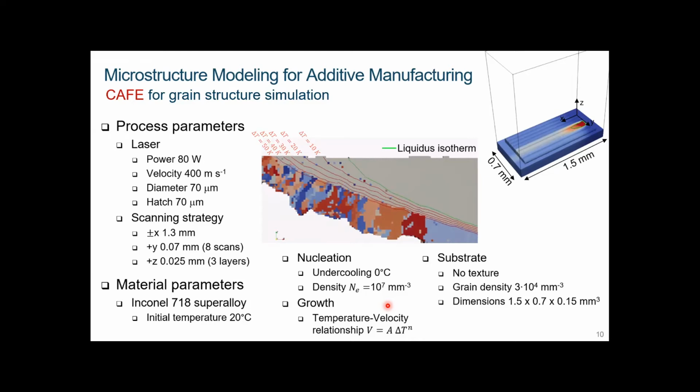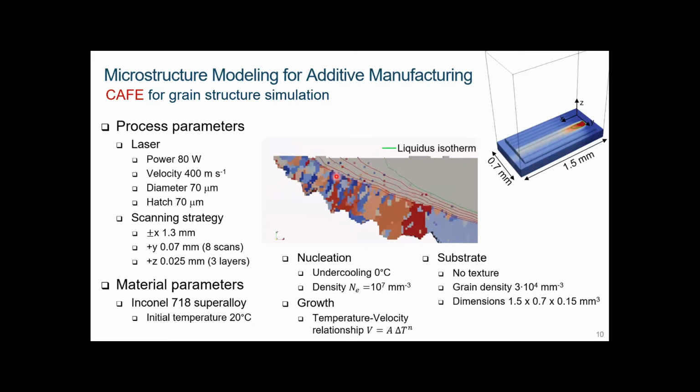Okay, so that's an illustration showing how the liquidus isotherm moves in the simulation. This is 10 degree undercooled, 20, 30, 40, 50 degree undercooled. So you have this columnar growth growing, and below the liquidus you may nucleate and grow equiaxed grain, and of course all these small dots you see here in color correspond to cells that have been captured either by growth or nucleation.